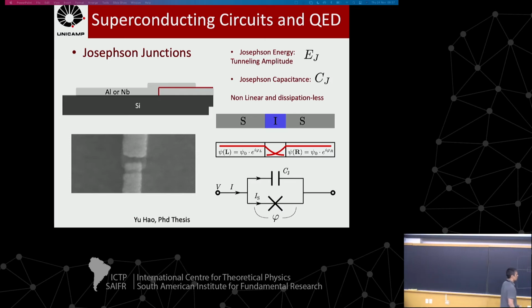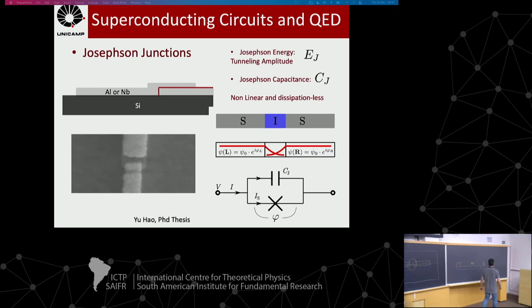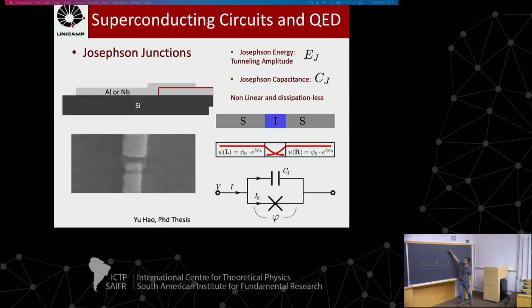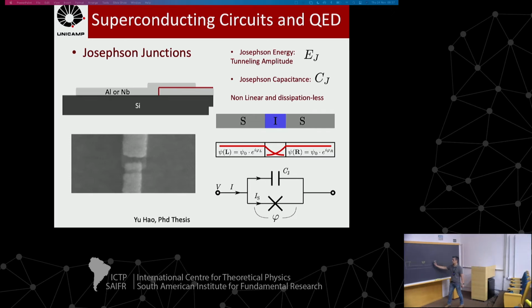So we put this sample in a vacuum chamber, and then we put in a source that will evaporate aluminum on top of this device. How will we do that? In our equipment I have a pocket here, and I put aluminum on the bottom part.